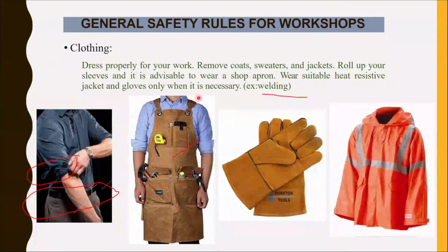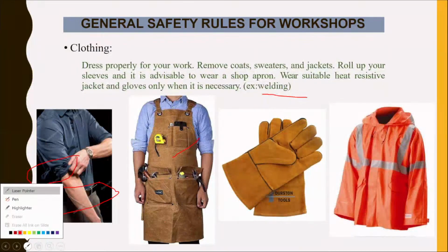And as I said earlier, you have to follow personal protective equipment and proper clothing. Okay, dress properly at your work. Remove coats, sweaters, and jackets. Roll up your sleeves, and it is advisable to wear a shop apron, right?